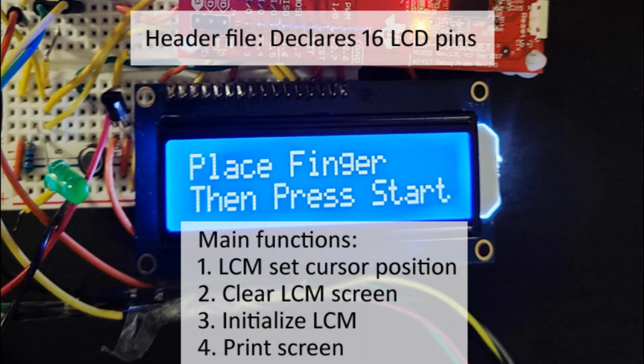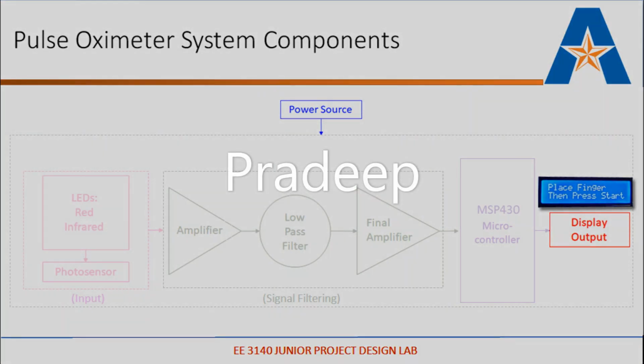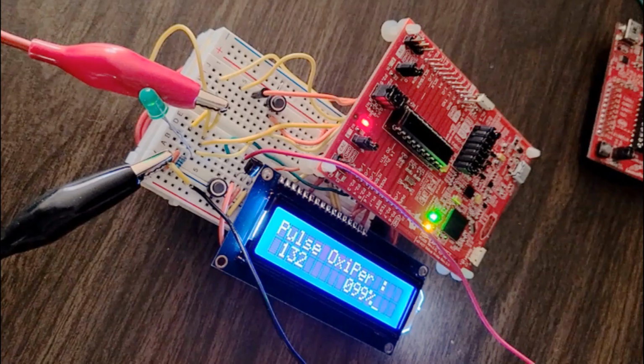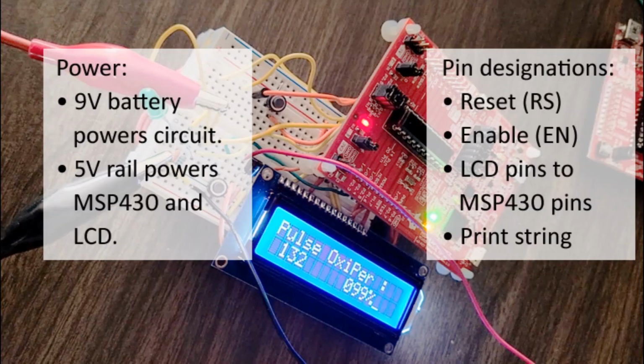Talking about the hardware, a 9-volt battery was used to run the amplifier circuit. A 5-volt regulator was used to form a 5-volt rail that would power the MSP as well as the LCD. The 4-bit LCD mode was used so that we could save more GPIO pins as compared to the 8-bit mode. There are altogether 16 pins for the LCD display.